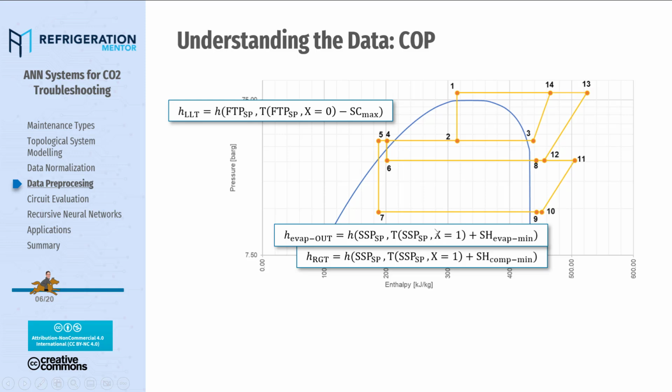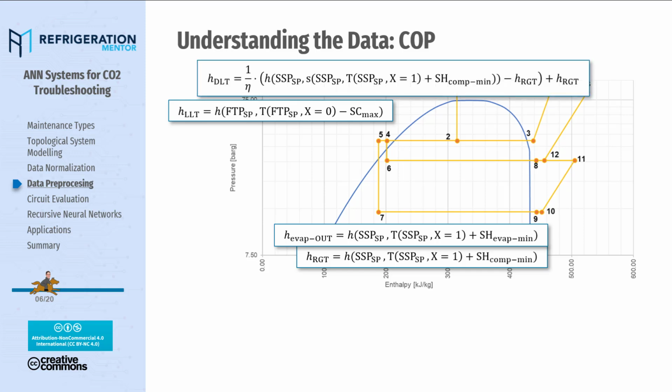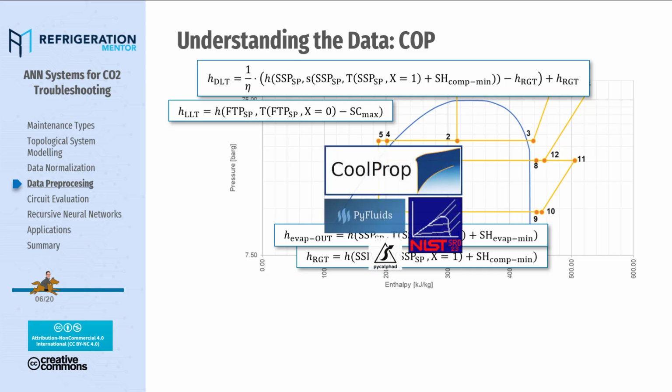Now, to calculate the discharge line, we must calculate entropy for suction and make some other corrections according to the isentropic efficiency of the compressors. So in this one, it becomes handy having the temperatures and pressures for the system and submitting this calculation to software such as Python that can manage components such as RefProp or CoolProp.